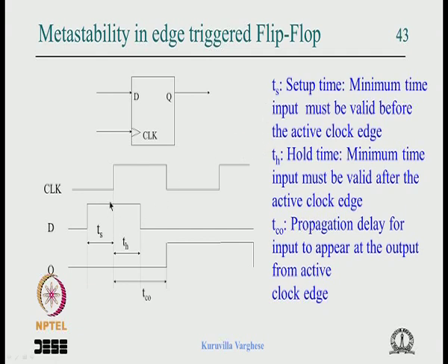It can upset the setup and hold time, and the worst effect would be that this output can get stuck at a voltage level which is neither 1 nor 0; it will be in between. That can drive any circuit, not even just a flip flop, it can even drive the combinational circuit's gates into the active region, and that will act as an amplifier. Any slight noise will start switching, and it will dissipate a lot of power. Maybe it is taken care of in the design, depending on how you design, but definitely this is quite disastrous, that it gets stuck in between.